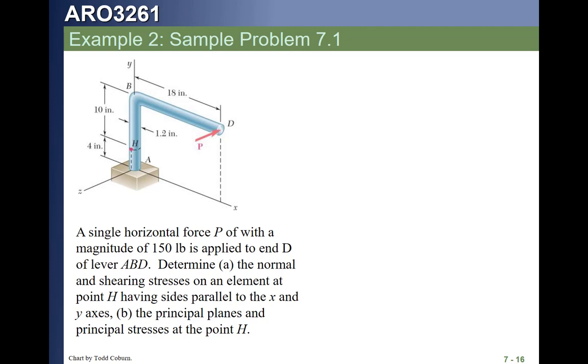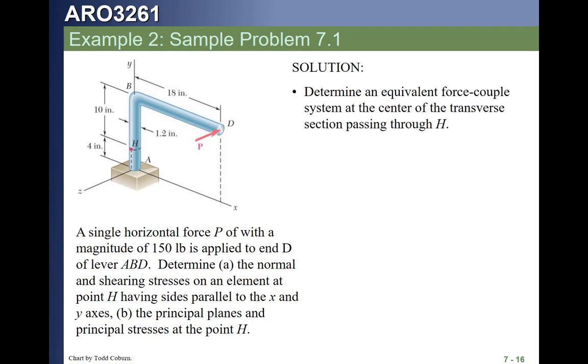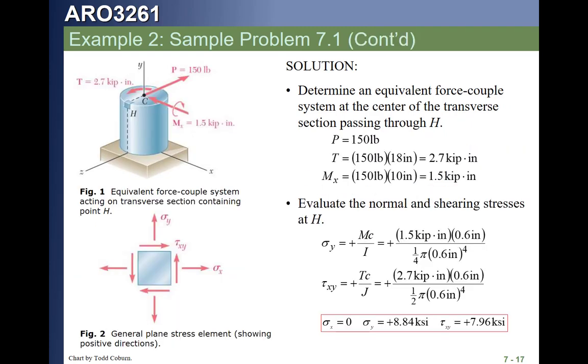Before we can evaluate stresses, we need to systematically make a section cut, draw a free body diagram, calculate our equivalent forces on the cut, and then apply our equations for shear, bending, and torque to figure out what the stresses are at the point we're talking about. This is our approach.